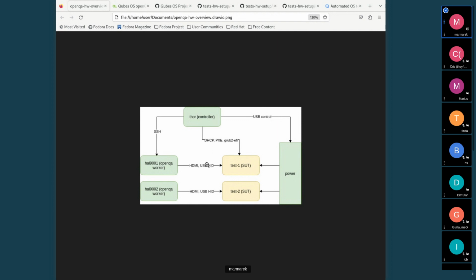And in some rare cases, I have a system that has a real serial console, and it's also connected to the Raspberry Pi, this one on the left. So I also have an interface to connect and capture serial output. If a serial console is there, it's the most convenient way to capture crash messages.